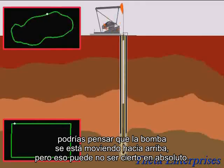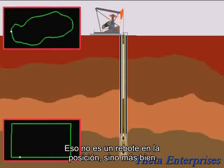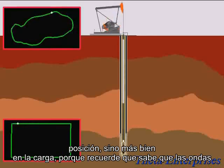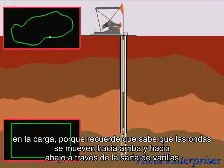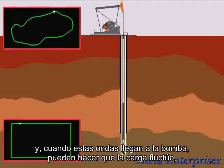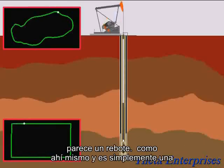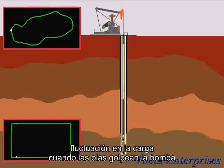What's the little bounce at the top of it? Actually, that is not a bounce in position, but rather a bounce in load. Remember, waves are moving up and down through the rod string, and as these waves reach the pump, they can make the load fluctuate. So sometimes you see what looks like a bounce, like right there, and it's simply a fluctuation in load as the waves hit the pump.